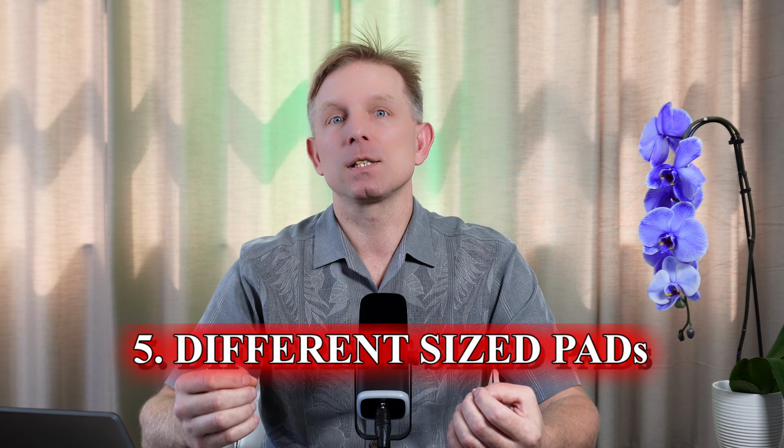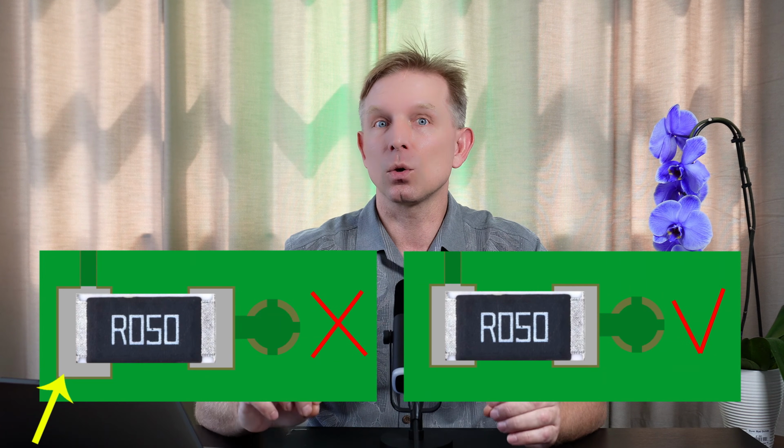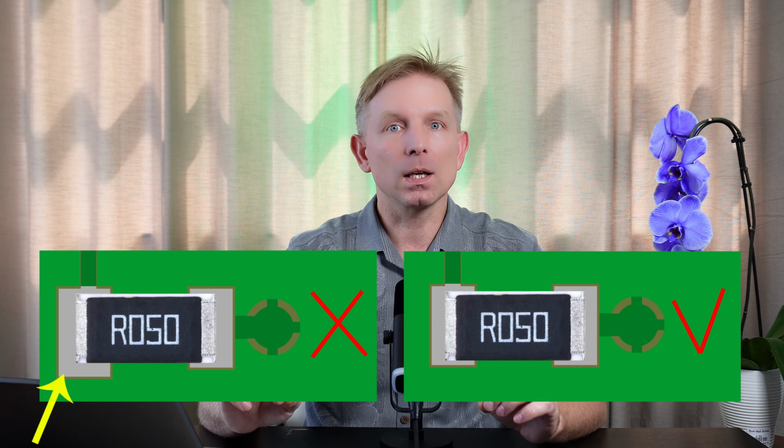Fifth cause: different sized pads of a symmetrical SMD component. Different pad sizes can cause a slight temperature difference. Another common mistake is different stencil apertures for the pads of a symmetrical SMD component. The result will be unequal volume of solder paste. This needs to be corrected at the PCB and stencil design stage.